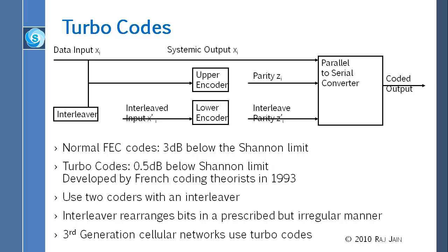So for example, in this coding, what we have done is actually, if you notice, the middle 2 bits are same as these 2 bits, 0, 0, 0, 1, 1, 0, 1, 1. Right? And we have added 3 extra bits. So those are the bits that we are talking about, the parity bits. Those are the extra bits. Right? So we take the original signal, we take the parity bits from the one coder, we take the parity bits from the second coder, and we combine all that and we send it. We can come very close to the Shannon limit.